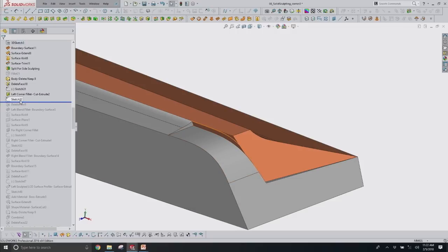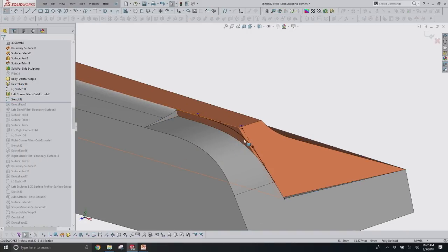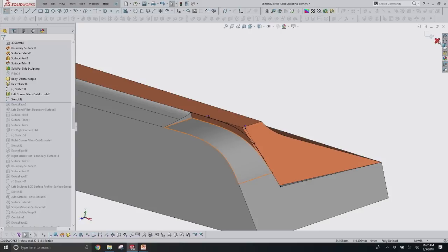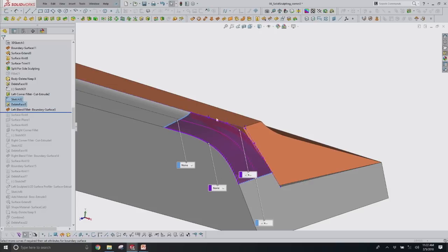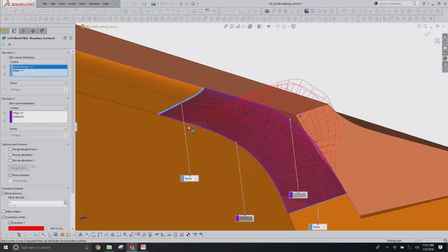It's a matter of a second sketch. Same thing we've seen before. Style spline tool with the equal on everything to build that nice G3 connection, entirely parametric. And then we're coming in with the boundary surface. So instead of relying on the fillet tool, and here I didn't select tangent or curvature to face, and I didn't select curvature to face here, and there's a reason for that.